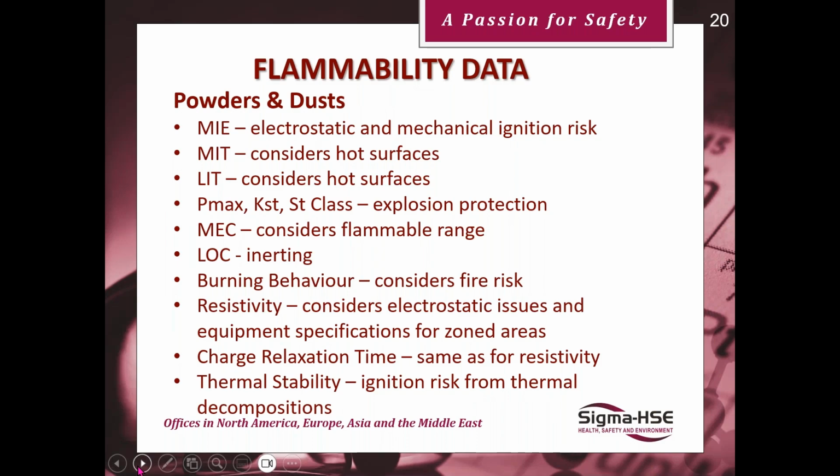The main thermal stability testing mimics the type of operation that you're doing. So we would have tests that mimic a spray dryer or fluid bed dryer or a ribbon dryer, etc. And then we can give you safe working temperatures. And the same for storage. Many instances I've attended where silos or storage hoppers have caught fire because they've been working even 2 degrees above the safe operating temperature.